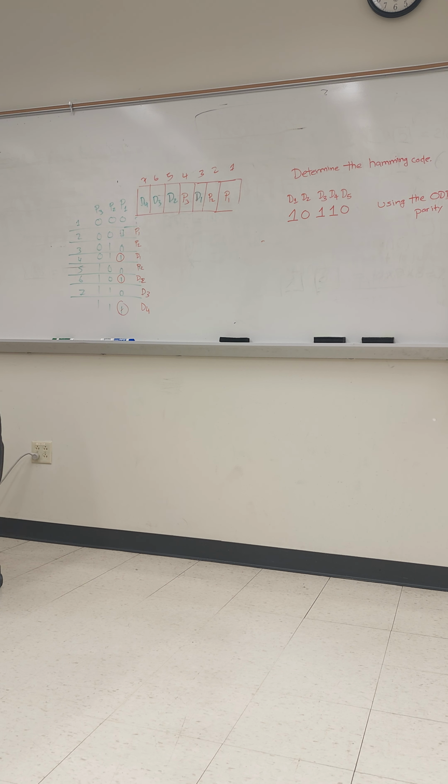If it is even parity, we should try to find out even number of ones. So the table on the left just tells us which parity bit corresponds to which data bits. Then to select the parity bit, we just look at the corresponding data bits. If it's an even number of ones for the corresponding data bits, we would make the parity bit a 1 to make it odd.